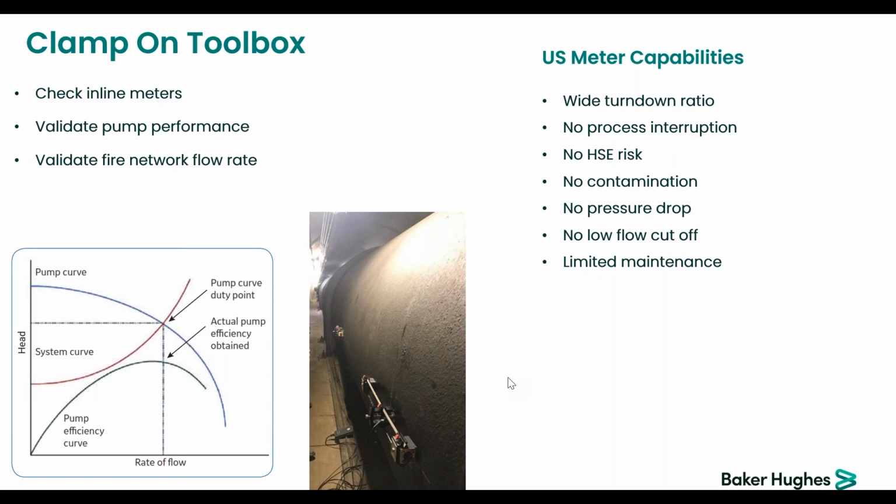And when you have your thickness gauge and you measure the thickness at different points, you have entered what the material is. If you have a coating on the pipe, it will have a different density, so it will not really be accounted for. So you may trigger a little bit of additional error, but our experience says that this error will typically be maintained within a couple of percent.